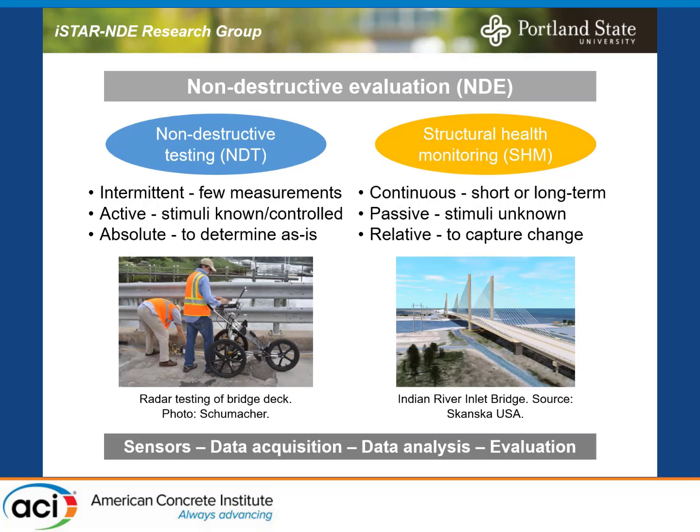With structural health monitoring, I see it a little bit differently. It's more of a passive process, but it's continuous, and it can be short-term or long-term. It could be during a bridge load test, where a truck drives across a bridge, for example, and we put instruments on and we monitor that process to capture deformations, strains, rotations, whatever we want to capture. It's passive in that the stimulus is often not known, especially in long-term monitoring. We really don't know much about what's causing what we're measuring. It also doesn't give us, for example, the state of the condition, it gives us a change in the condition.